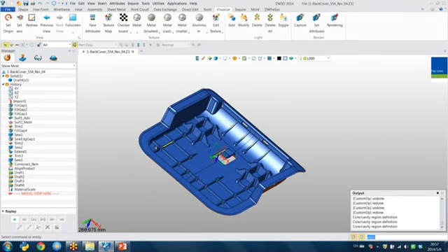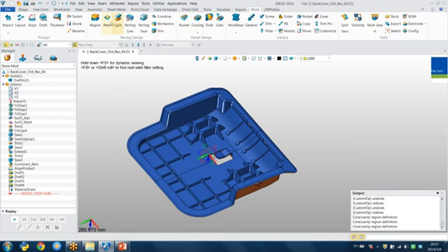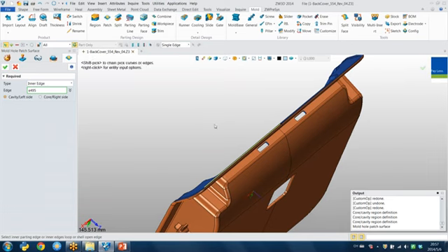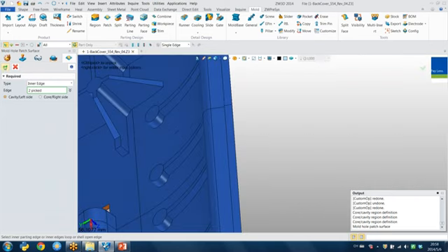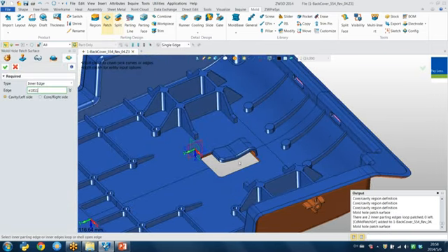So next, okay, we need to use the patch functions to correct the surface. So you can find for the spline, you just need to select the edge. It will create the patch automatically. For the inner, this one also the same. And you can find they have 2 options: cavity left side or core right side.